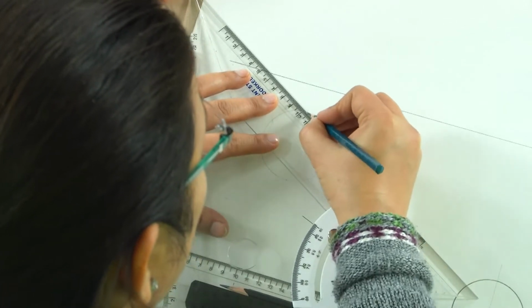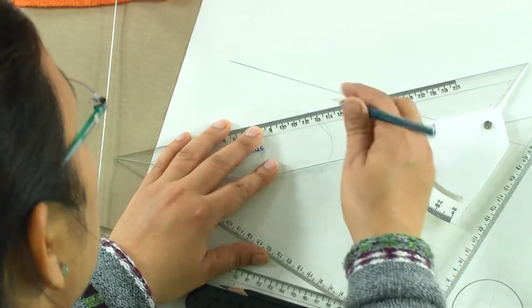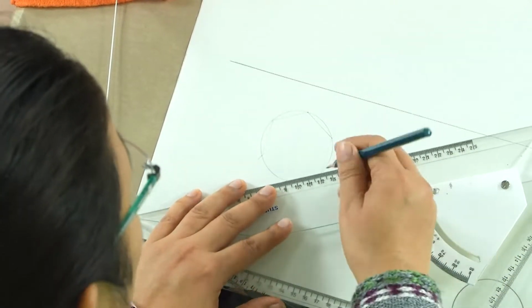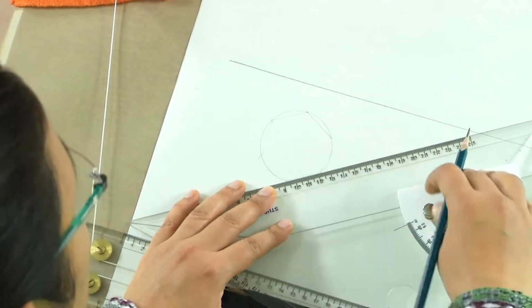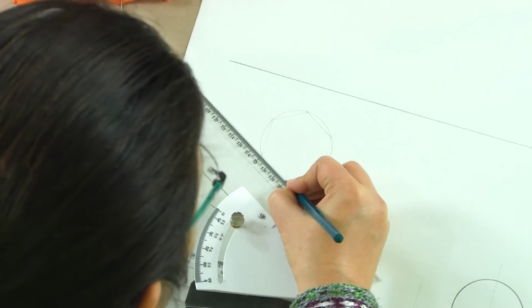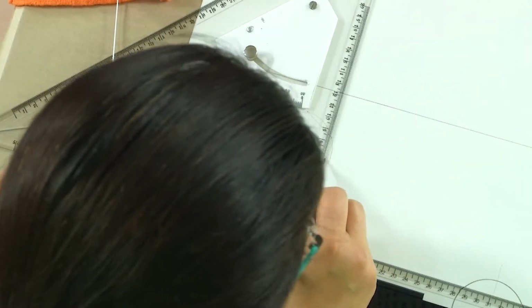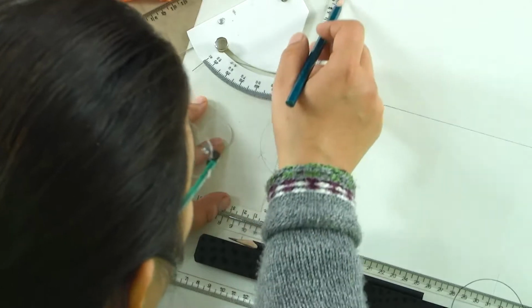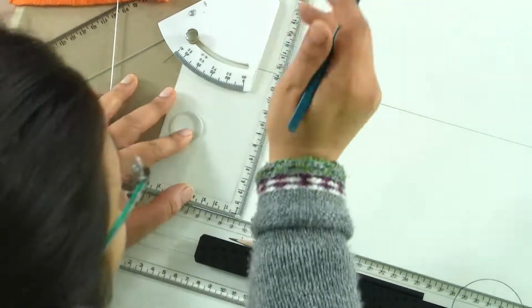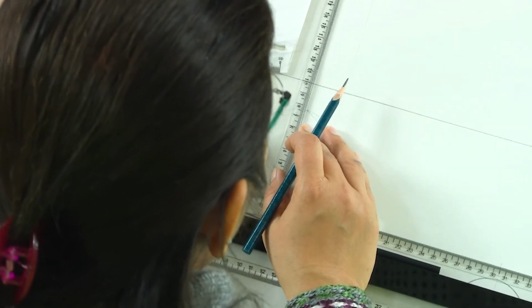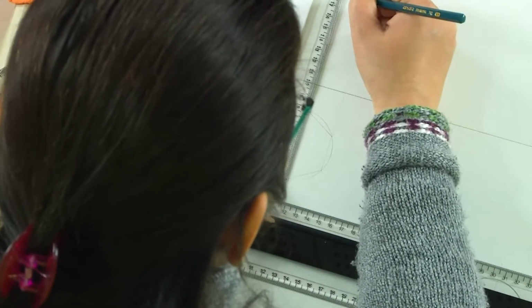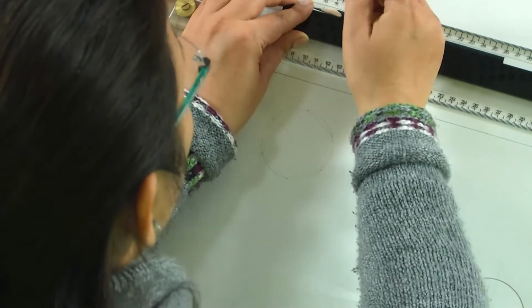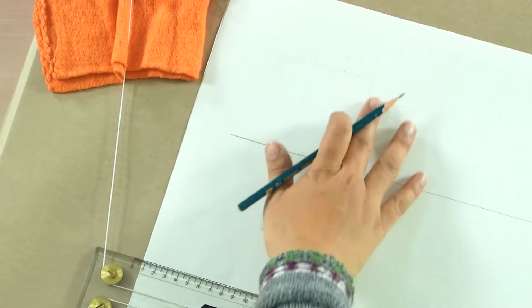Since this prism is kept perpendicular to HP, its base is going to be parallel to HP, which is what we are seeing here. So, we draw a solid prism. I am not darkening it because this is not the final thing, and in the front view we will be seeing the projections of this hexagonal prism. Assuming the height of the prism to be, say, 8 centimeters, we now have the front view of the prism as well. So, we now have the plan and the front view of the prism.